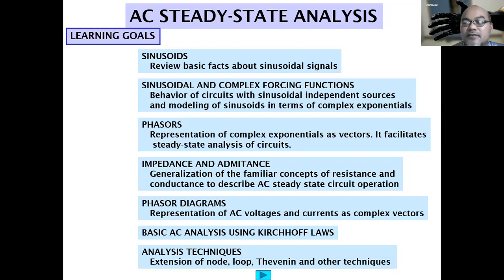When the circuit is connected to an AC source, either an AC voltage source or an AC current source, we learn how to use Kirchhoff's laws to solve for the electrical parameters. In this kind of circuit, it is changing with time because it is alternating current, but what we care about is only the amplitude, the frequency, and the phase. This is basically what we call steady state analysis, because it doesn't vary with time as in the previous chapter, where it was an exponential of minus t over tau, where there is a tau there, etc.